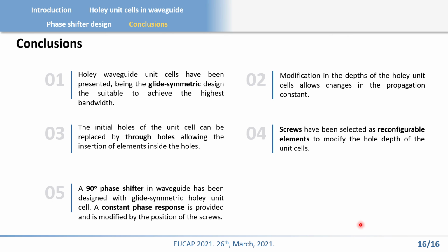In this final slide of the presentation, the conclusions are enumerated. The most important conclusion of this work is that a wideband 90-degree reconfigurable phase shifter is obtained thanks to the use of Holey Glide-Symmetric unit cells based on through holes where reconfigurable elements can be inserted.